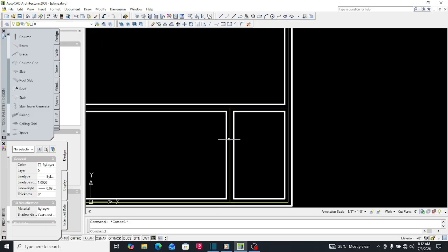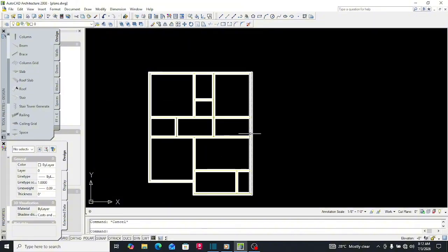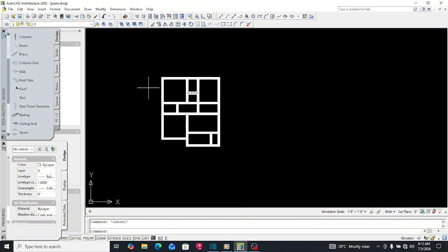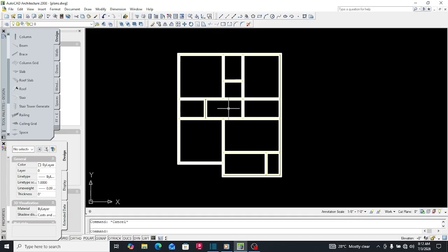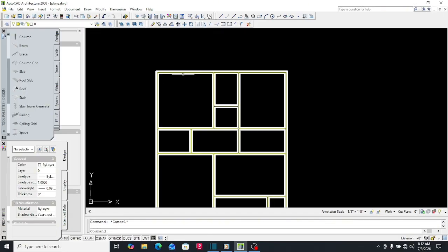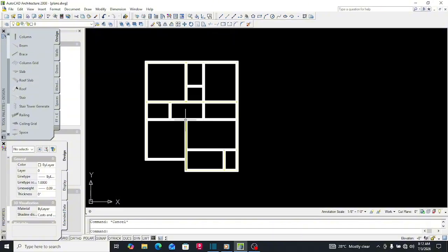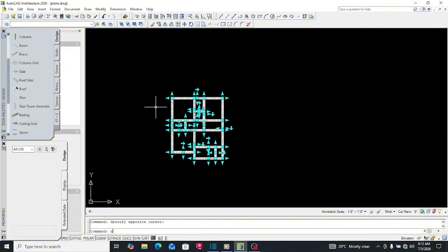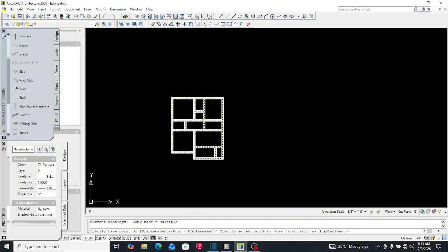I think you can even remove this, but since it's a tutorial, I will just leave it there. So this is how the foundation plan should look, after removing the doors and the windows and introducing your sleeper wall. If you don't have to introduce a sleeper wall, just leave it like that, and then you copy it again, then send it.